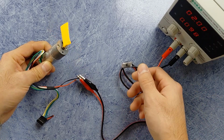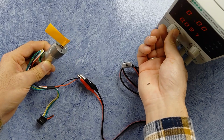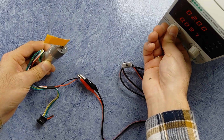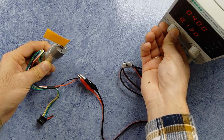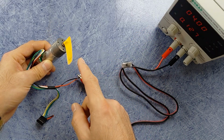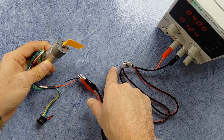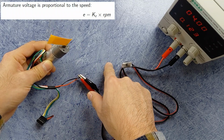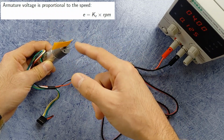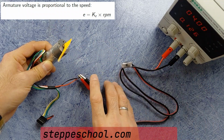But what I will do is just increase the voltage. It's 2 volts currently. I will set 4 volts. And what's happening is that it started spinning faster. From this observation, we can write our first equation: the armature voltage is proportional to the RPM, the rotation speed. So if we need faster rotation, we need to increase the voltage. Okay, this is our first observation.